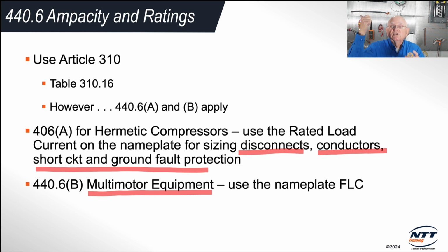And what it's doing is rejecting that heat that's been brought in from the building. The compressor takes that low pressure vapor, compresses it, and sends it up to the condensing unit. A fan blows air across there, and it rejects that heat that's been collected out into the surrounding environment. Then that refrigerant goes on down and cools our building again, just a complete cycle. Well, that's all part of that refrigeration cycle that we won't get into in this presentation. But anyway,